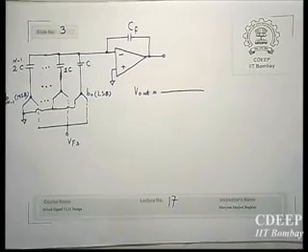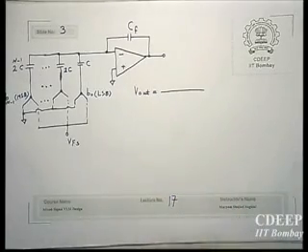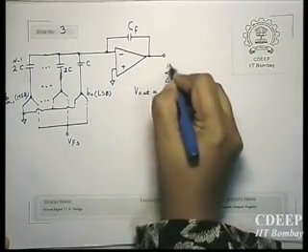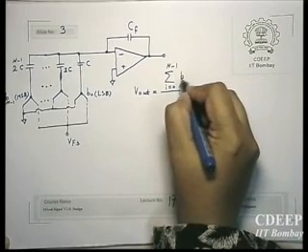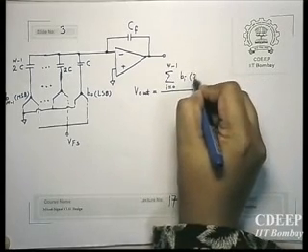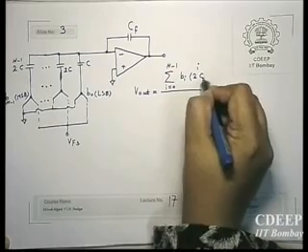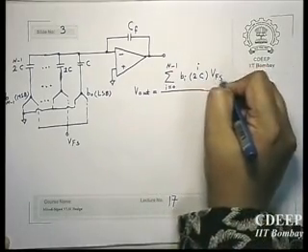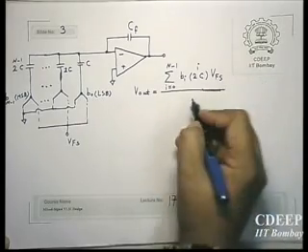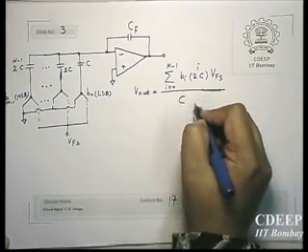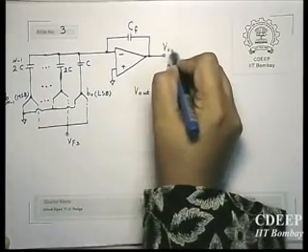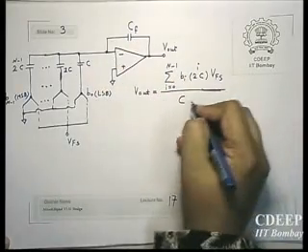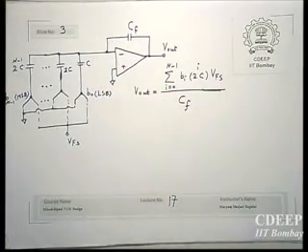Therefore, total charge, which is Q, in general equal to CV, we write it here. So i is equal to 0 to n minus 1, Bi, which is the input bit, to the power i, into C into V full scale. This is the total charge which is also transferred to CF. Therefore, divided by CF will give you V out.